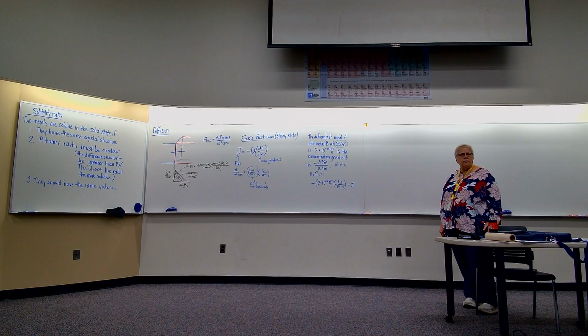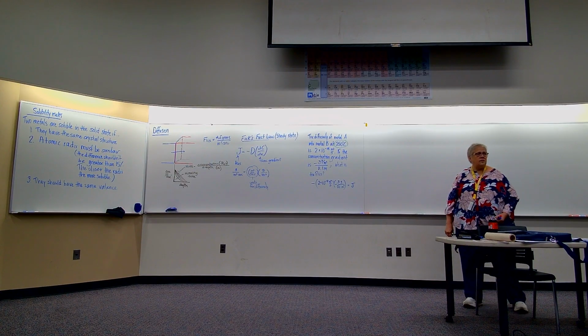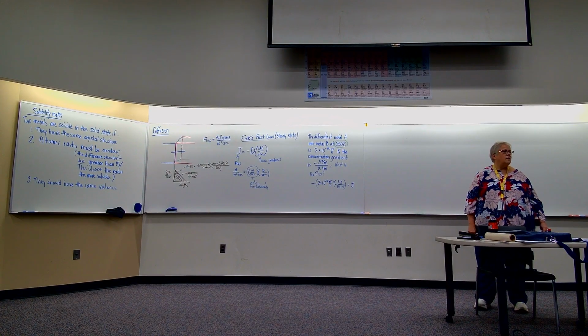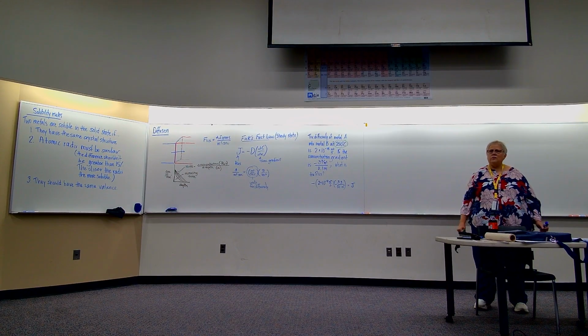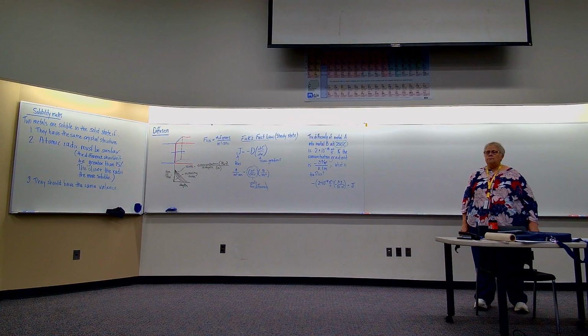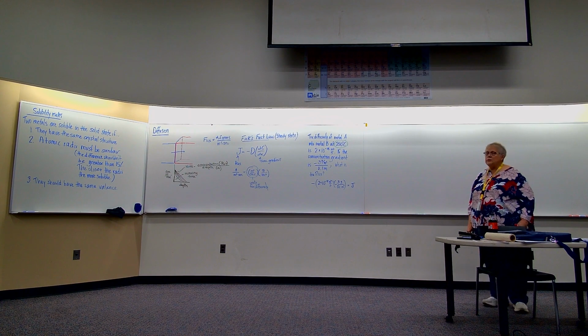Why would the rate at which an atom moves into a solvent change with temperature? What would cause that to change? Because if you add heat, the atom starts moving faster. All the atoms are moving faster, so the chances of it moving by accident into whatever we're diffusing into increases.